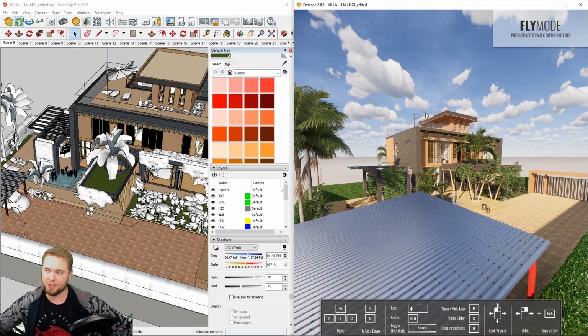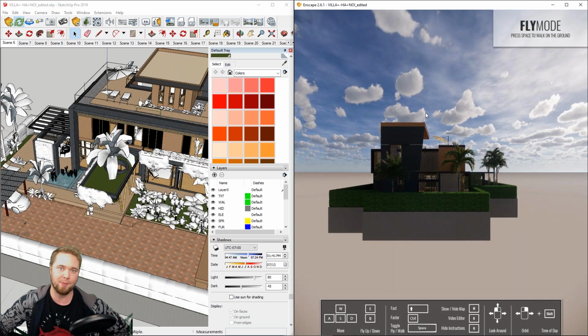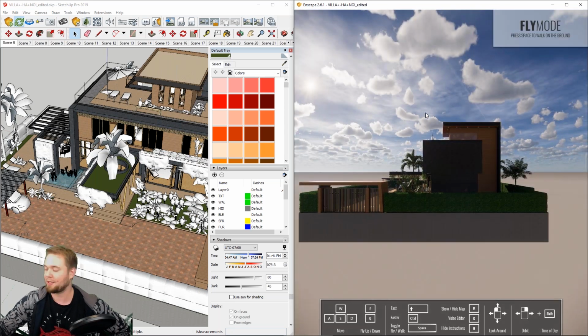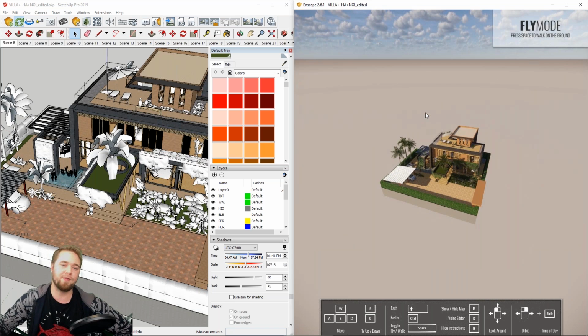So just to show you what it does, I'll press 4, and that shows the project from the left side. You can imagine like the 5 being your project, and the numbers around it looking towards it, sort of. So 8 will view the model from the back, 6 from the right, 2 from the front, 5 will view it top down, and 0 will return you to the view you started with.